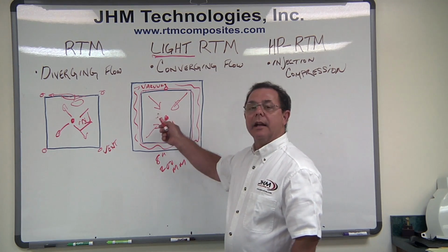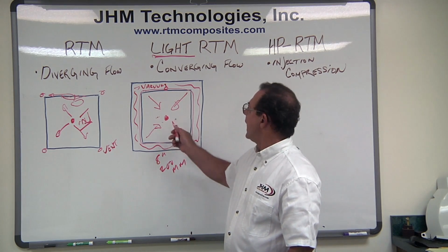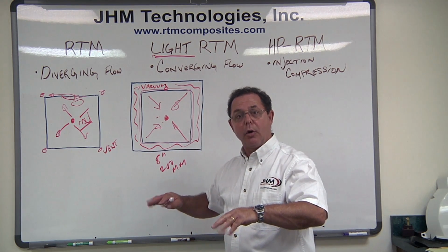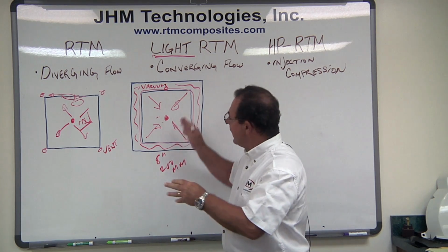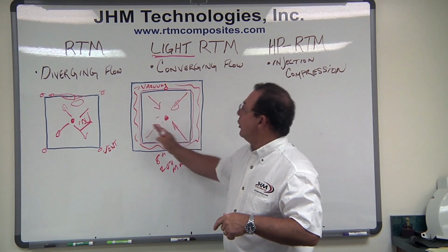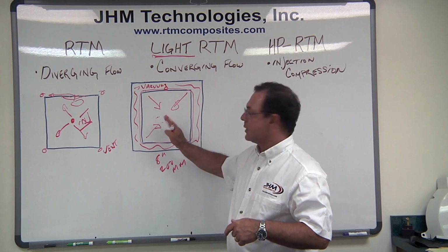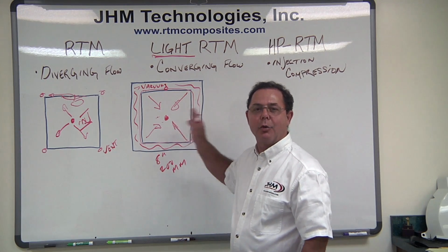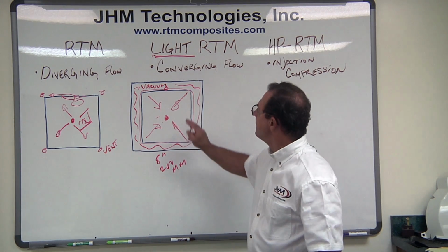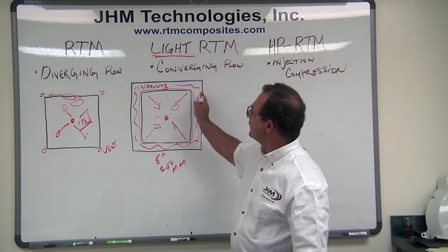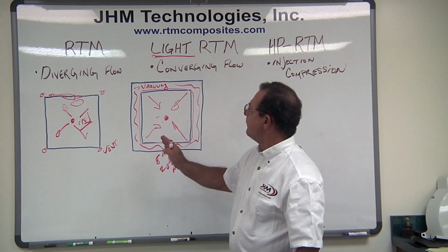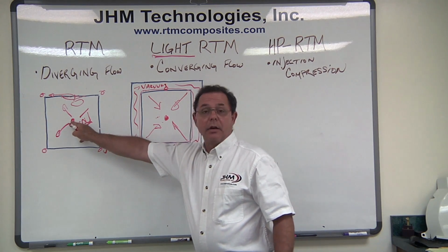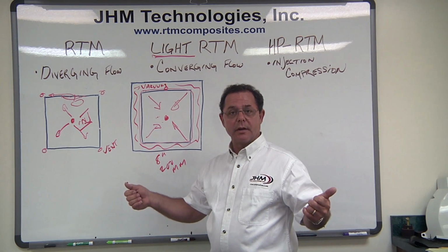We're also drawing a controlled level of vacuum on the cavity. So initially, we've got the entire mold areal surface holding the mold closed in a clamped fashion. And as we fill, we start to lose that advantage of vacuum in this area because we're filling it with the hydraulic force of the resin, which gets into another series of discussion about how to have your equipment control that flow rate, but that's not what this is all about. What we're going to talk about here is just the fact that the difference in the tooling is this clamping around the perimeter, where here we had to create full mold structure. And by injecting here in the center, it took even more pressure to force it to the edges.